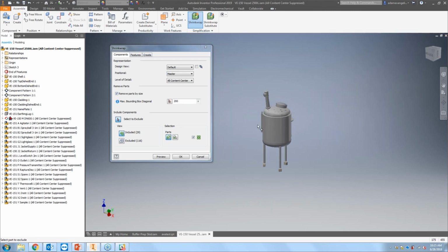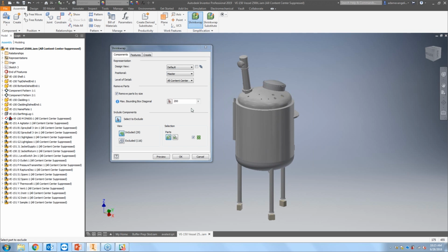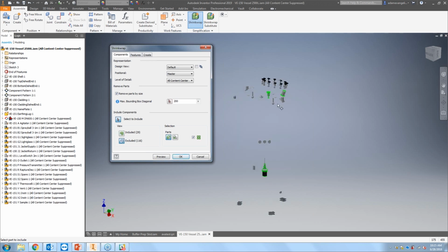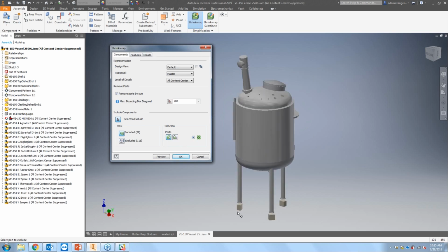And we're looking nice and clean, you know, we're looking pretty good. And so that said, those are the components I decided to include and exclude. You could also choose to view some other stuff. So you can see the parts that you just removed over here. You could choose part priority, or if you want to choose the number of instances, that's what this checkbox is here for, right? And if I uncheck that, you can see it's only one of the legs now.